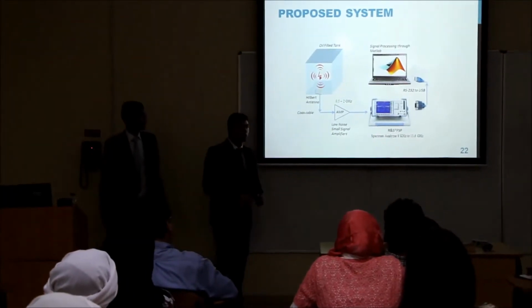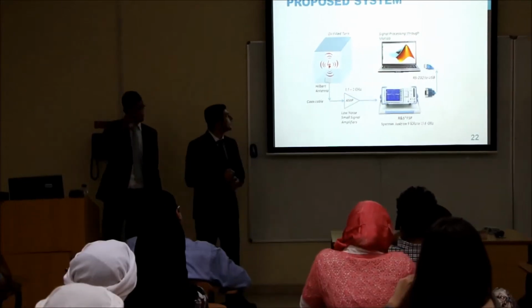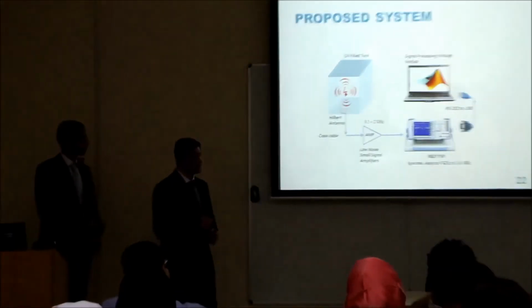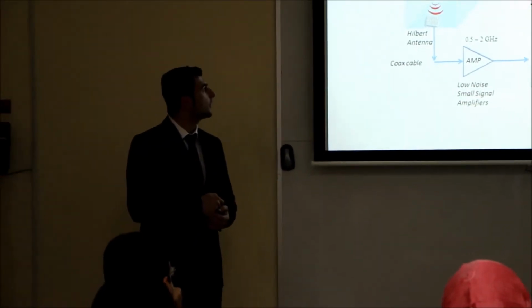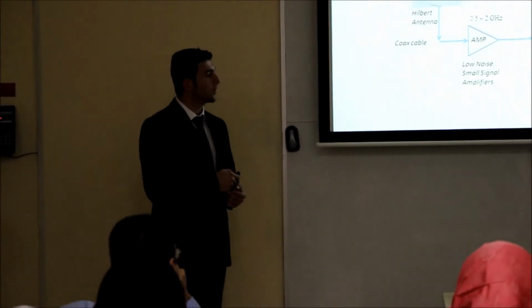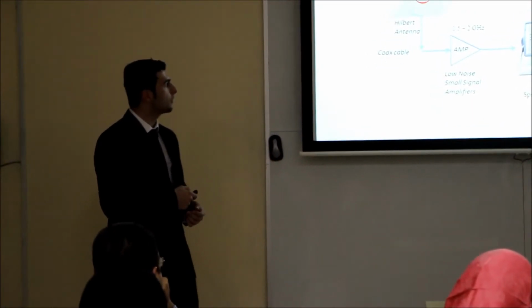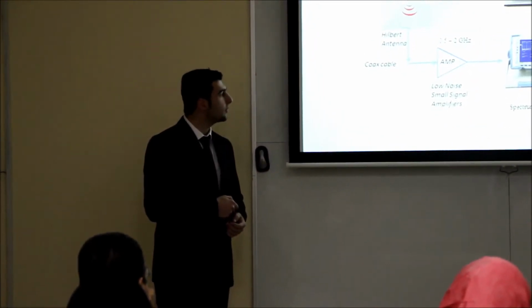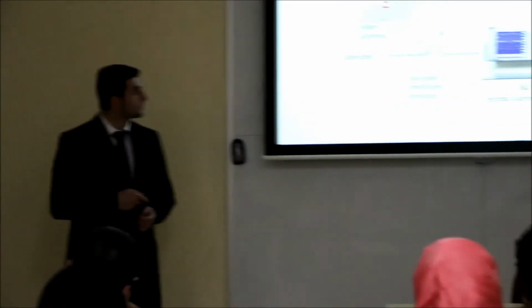Thank you, Mustafa. Now, our proposed system for the measurement of partial discharge is composed of the oil-filled tank, where the partial discharge signal will be artificially generated inside. The antenna will be placed at the bottom of the tank to capture the signal and send it through the high-frequency amplifier through a coaxial cable. The high-frequency amplifier will feed the signal to the spectrum analyzer, where it will be digitized and sent to the